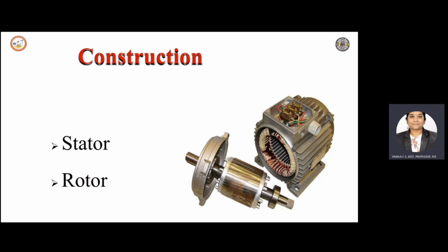The important advantages of these three-phase induction motors over other types are that they are self-starting. They need not have a starting device, like we have for a synchronous generator, where we use a prime mover at the time of starting. We also have better speed regulation, and the construction is very robust.